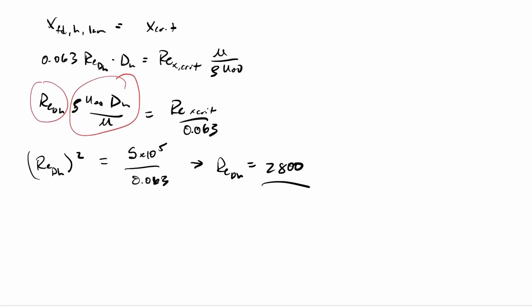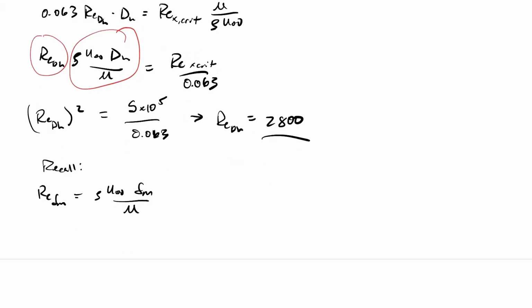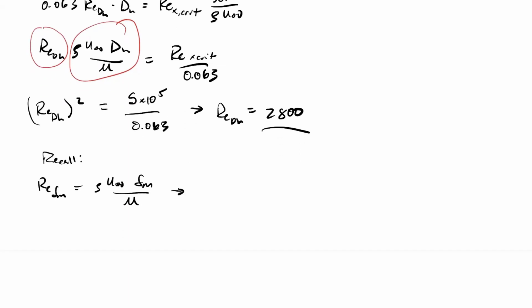Yeah, actually, one thing. Just recall that when we calculated Re in terms of delta M, our Reynolds number expressed in terms of the boundary layer thickness, we decided that was rho times U infinity times delta M over mu. Back in our analysis, we decided that the critical value, Re delta M crit, was something like 3,500. So if you go back in your notes, and I'm sure you will, look at that, and you'll see that those two numbers actually are pretty close, right?